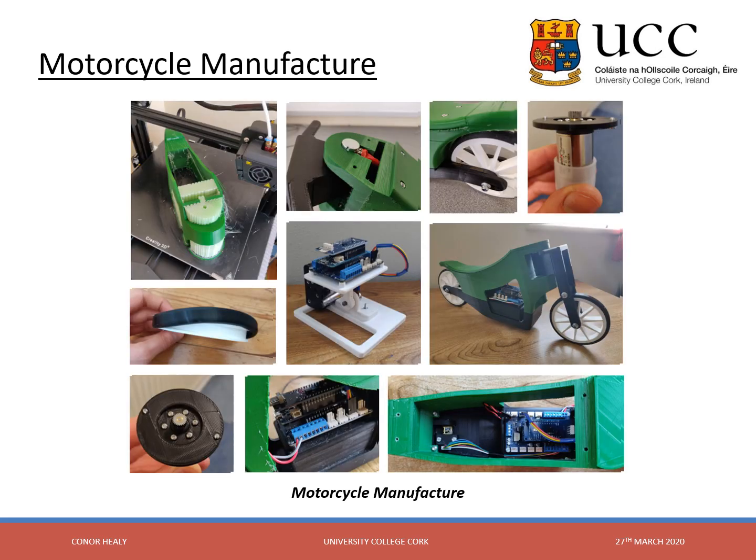The motorcycle was designed so the majority of its parts could be 3D printed. Dual extrusion with water-soluble support filaments was used. Most of the parts were printed using a rigid PLA material. However, a flexible TPU filament was used for the tires to give them more traction.